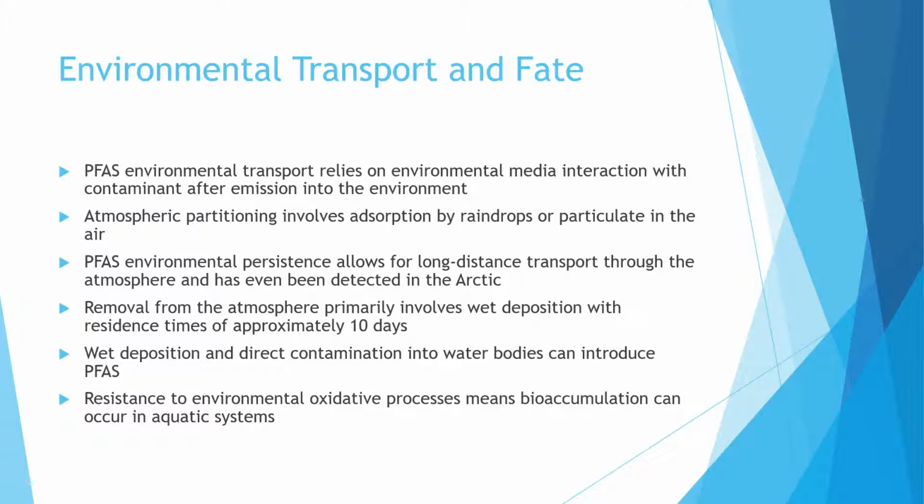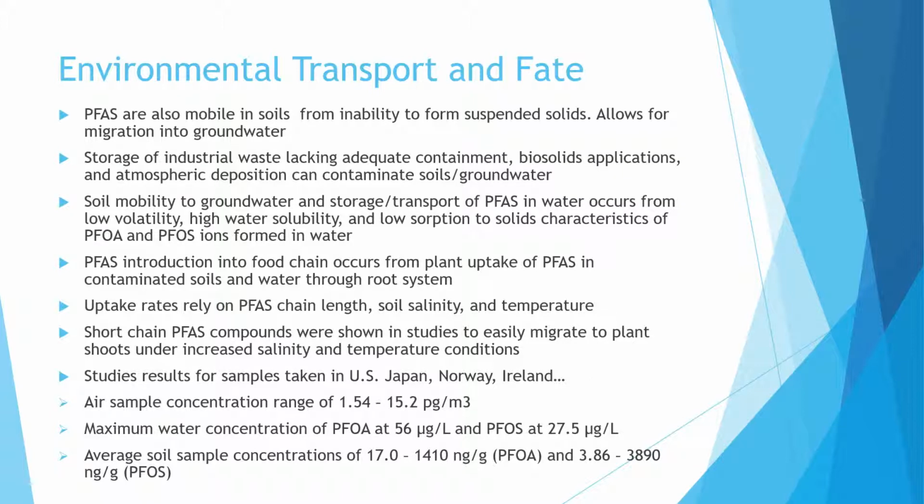In water, they can be introduced either through wet deposition or direct contamination. They are also resistant to oxidative processes in water environments. This means that these compounds will likely bioaccumulate in aquatic systems. For soils, PFAS are also mobile, and this is usually from the inability to form suspended solids. So these compounds cannot latch on to soils and be permanently fixed. They're able to migrate through the soils and typically into groundwater sources.